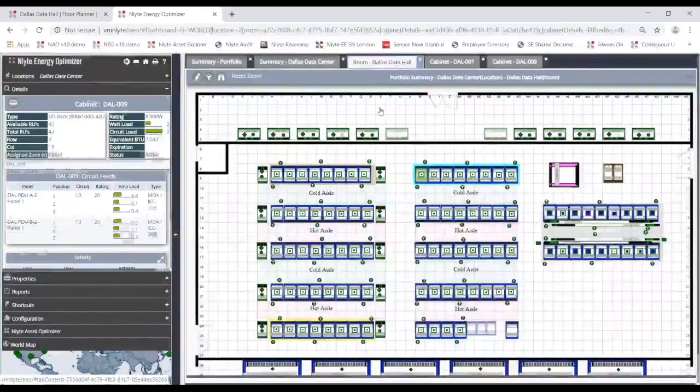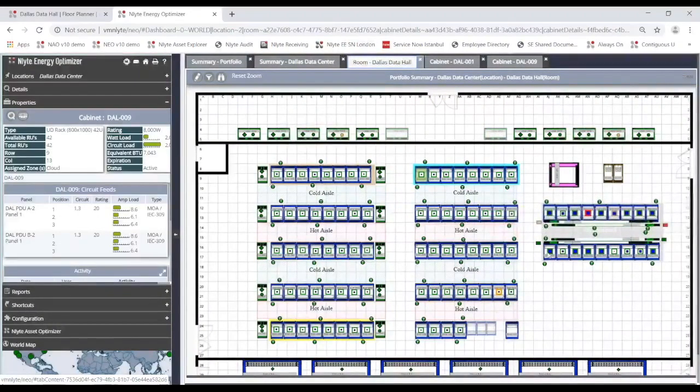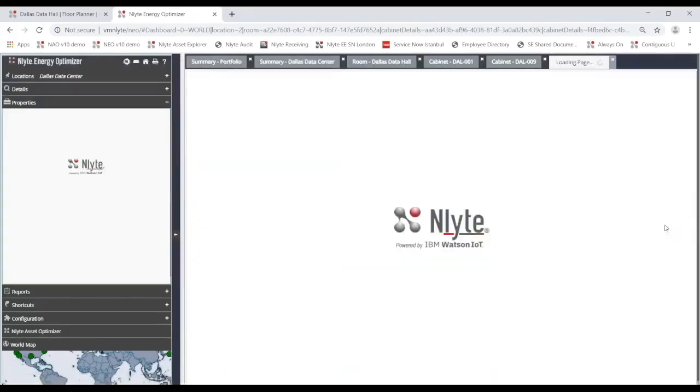And then finally, the third way that we monitor power distribution to the rack is through busway. So if we take a look at the end feed, we're able to show tap-offs as well, right? We can look at not only the end feed for the busway, but also the individual taps going to the individual cabinets.